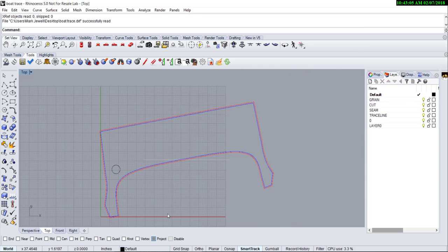Now it works on curved surfaces, as I showed in the previous screen with the boat where I did the porthole cutout, but it'll trace on a curved surface or any surface that you need. And all you have to do is in Rhino use the project command, and then use this pencil trace, the trace model command in Exact Flat for Rhino. Hope that answers the questions.